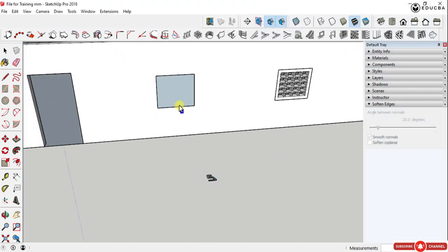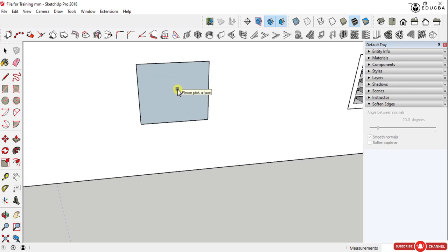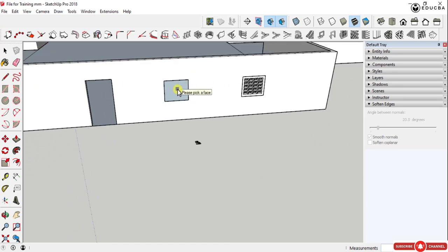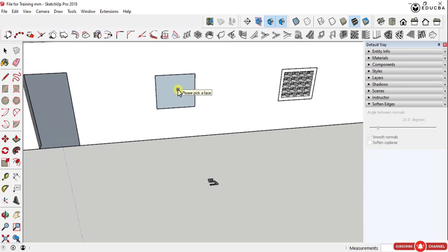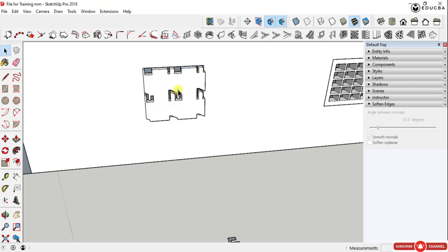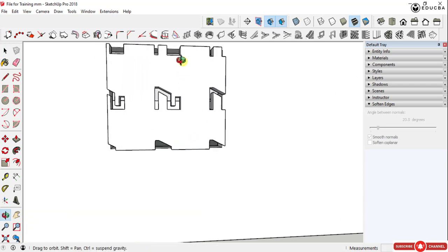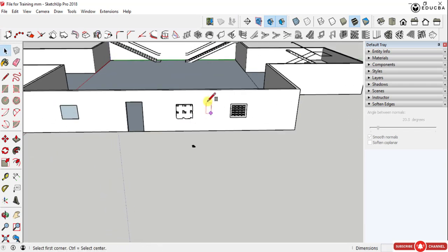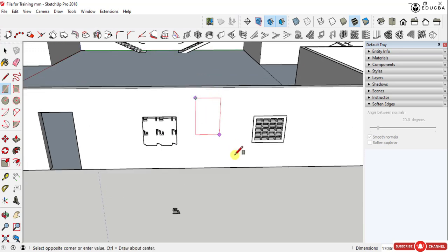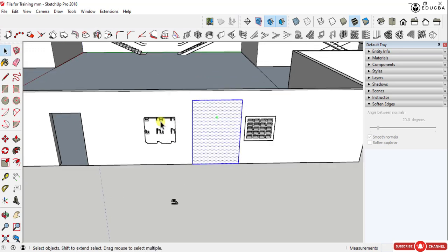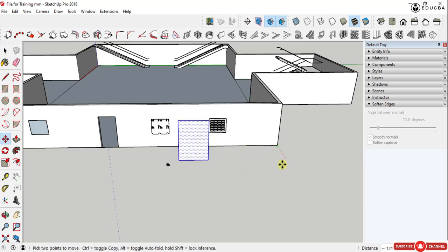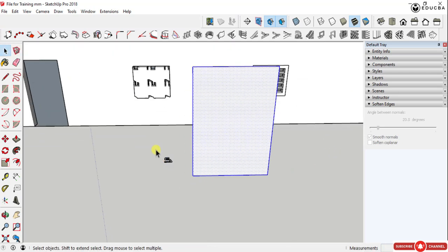choosing this surface, and the moment you scroll down and you can detect the other surface, the square on the cursor turns blue, which indicates the surface is ready to be punctured. And the moment I click, you can see there is this puncture, or I can create a larger surface, a pretty large one. I'm going to move it out as an individual screen.